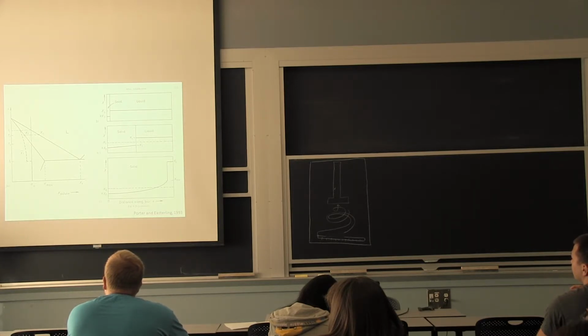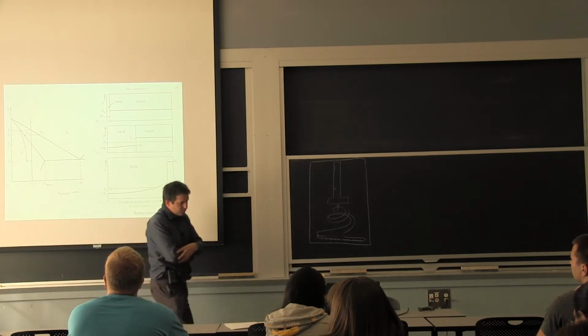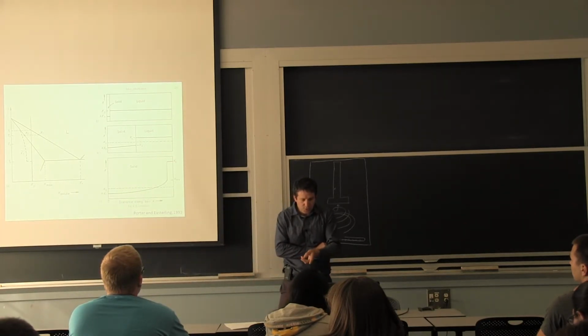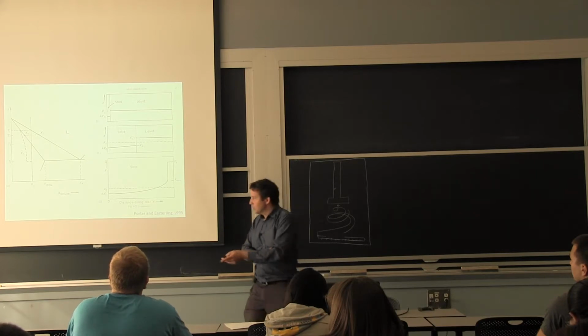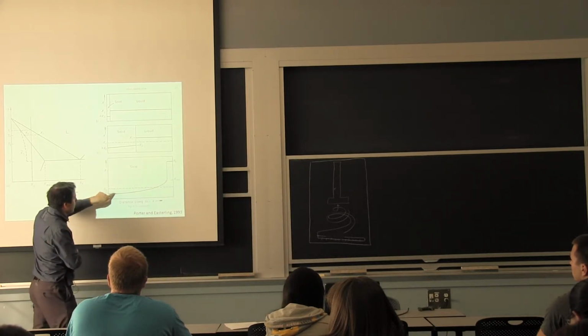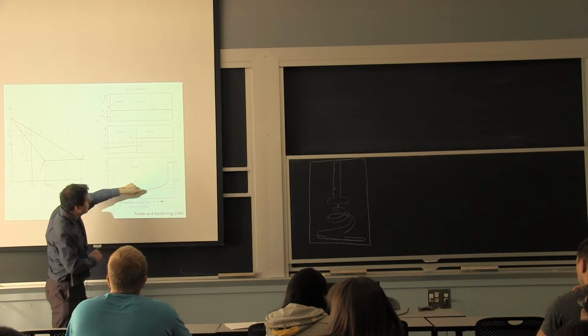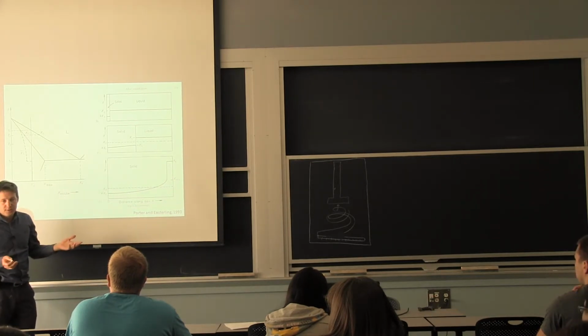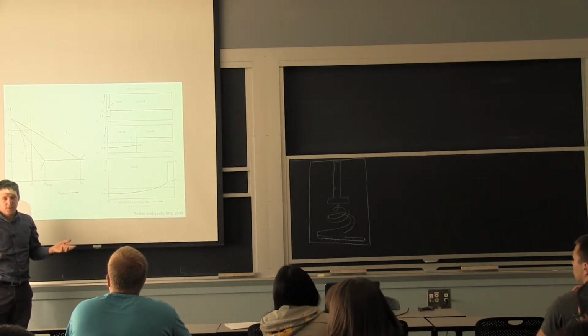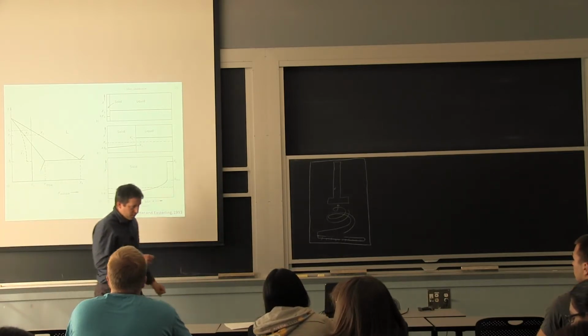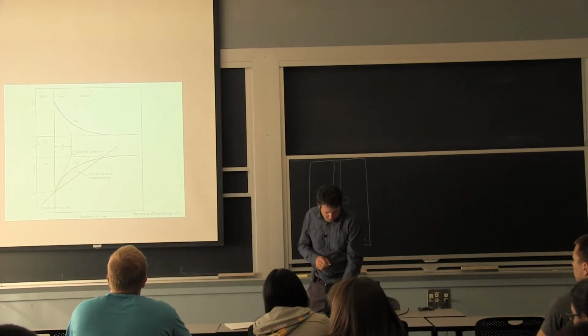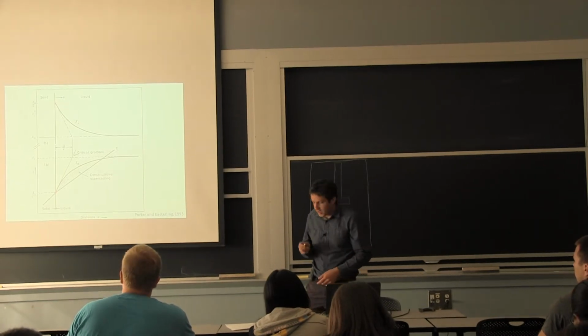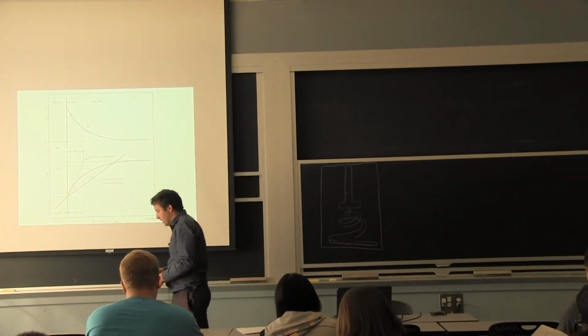And we have to work around the physics here with the thermodynamic stability of the different phases. So this will happen. In this example, it's two-dimensional. So when we see here that the bar composition looks like this, it's assuming you're not forming the dendrites. But even without dendrites, you have segregation, and that's the point I was really trying to make with you guys. Now, about forming dendrites.